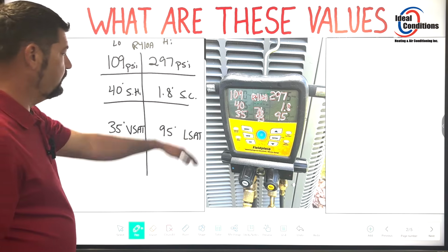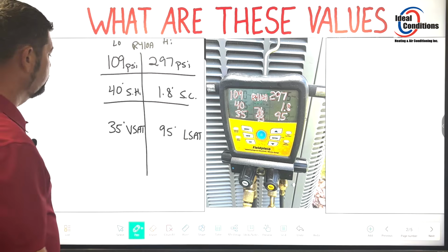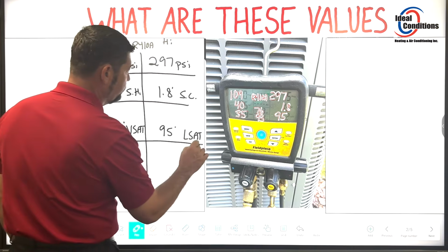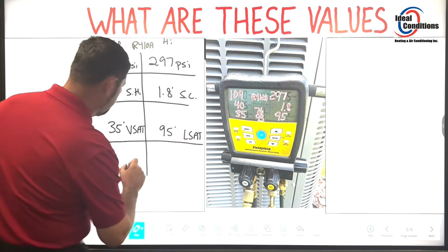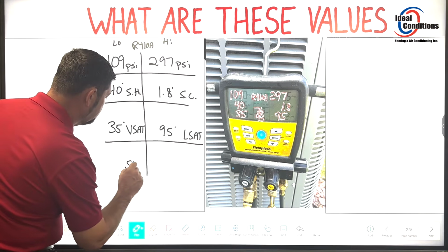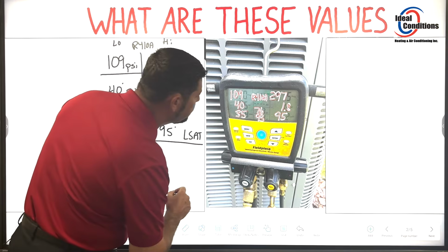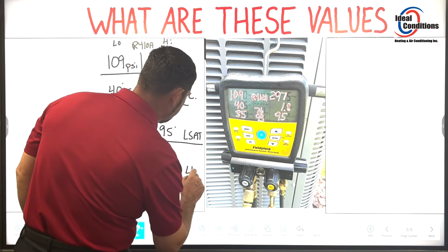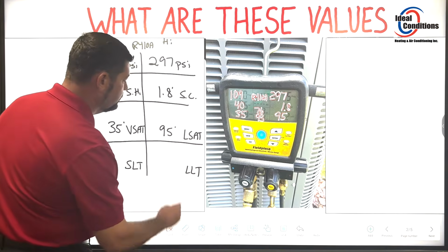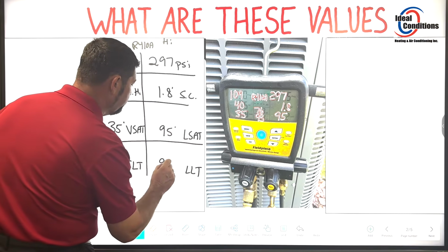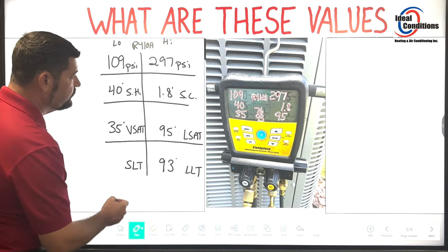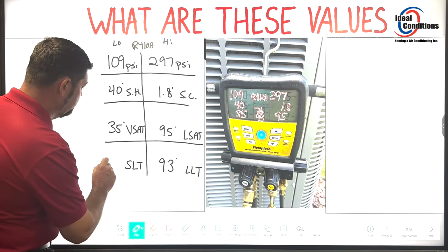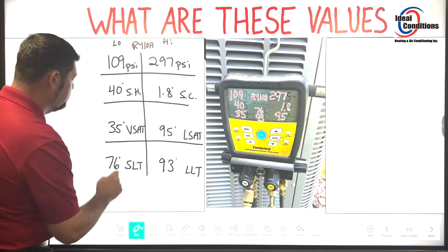Don't worry about these other values. I guess we can write them down. It's not going to hurt. All right, so we have suction line temperature and liquid line temperature. The liquid line temperature is 93 degrees. The suction line temperature is 76 degrees.